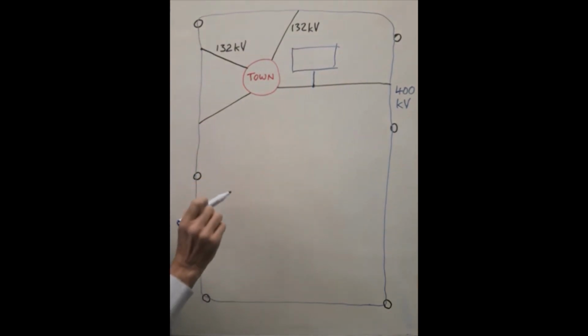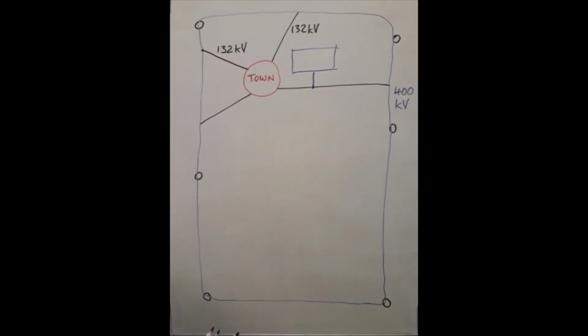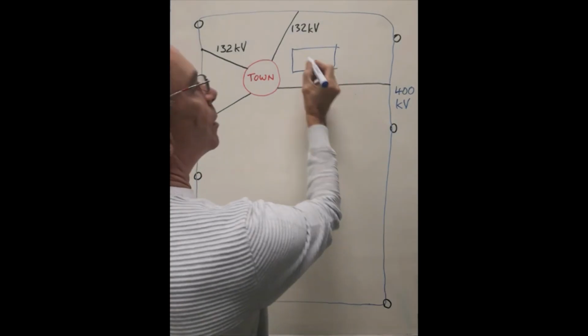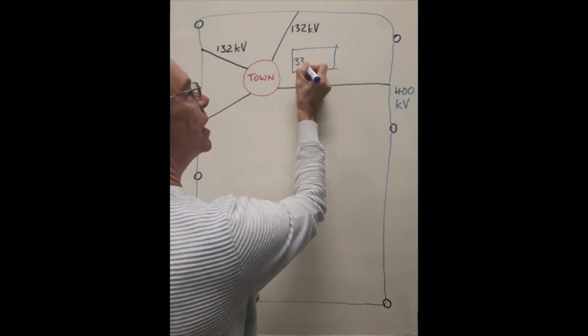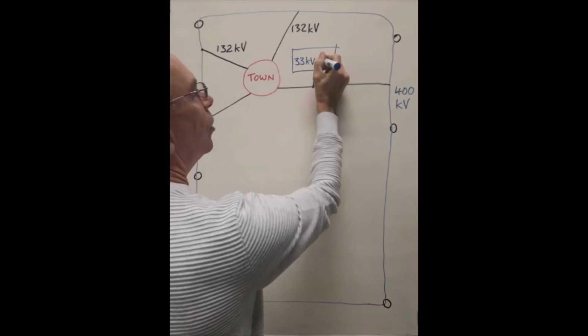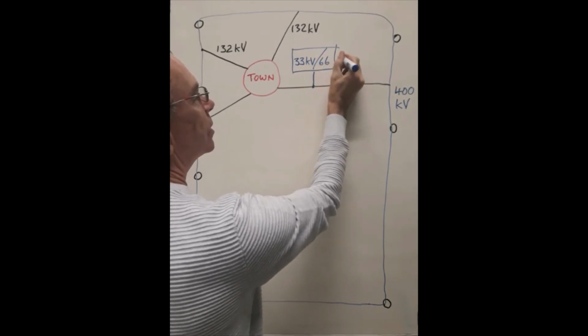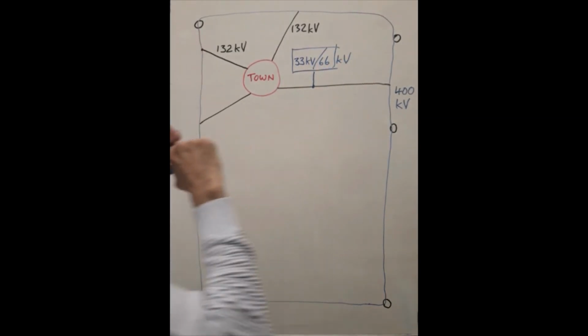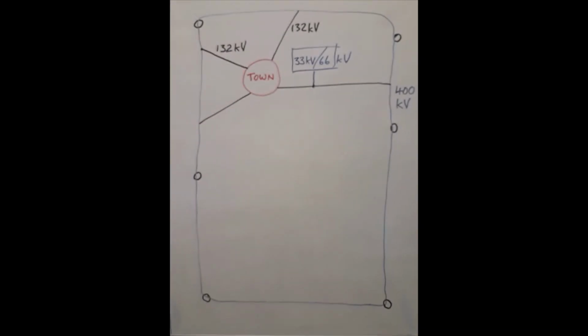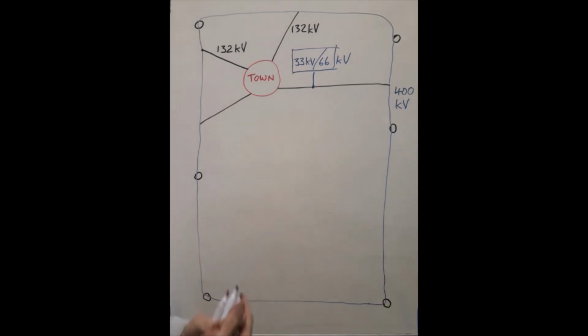This could be something like a steel plant, a coal mine, a car plant, perhaps railways, very large enterprises which consume huge amounts of power. These will usually be fed at either 33 kV or 66 kV. So quite unusual and very high, very dangerous voltages still. This would normally be on the outskirts of a town.